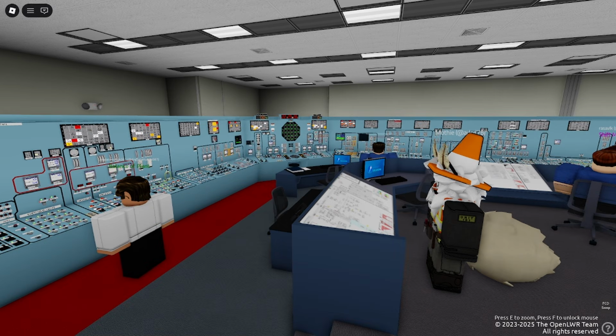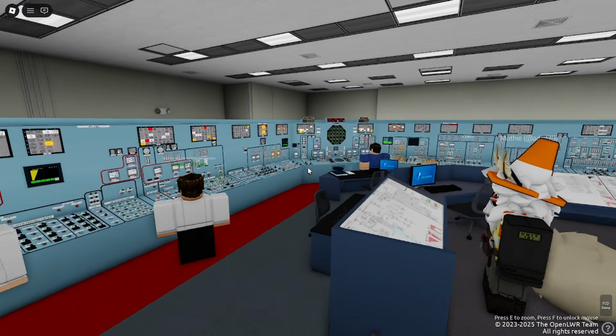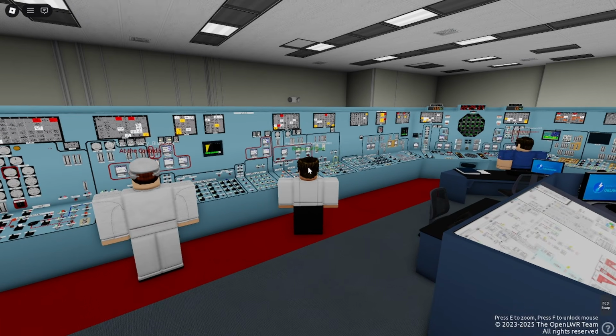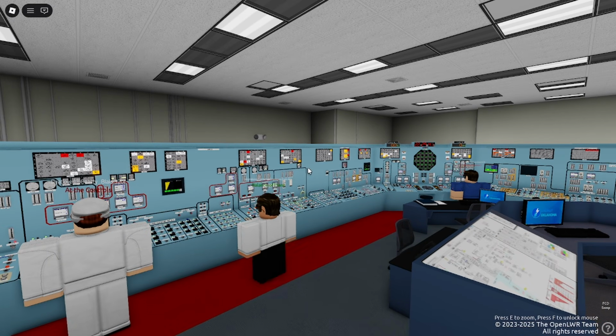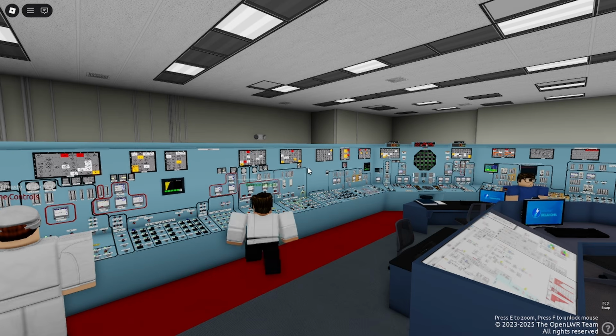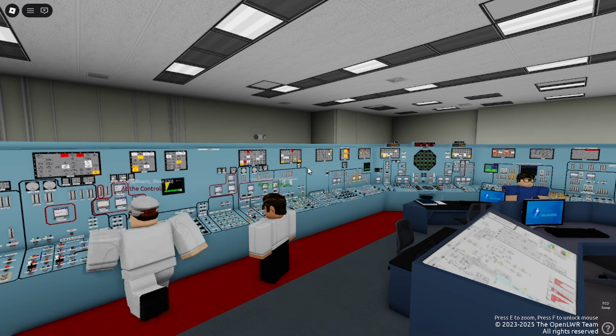Alright, can you control RPV pressure using SRVs? Keep RPV depressurized using SRVs. That's correct. Determine radiation levels in the drywell. Determine radiation levels in the drywell. That's correct.